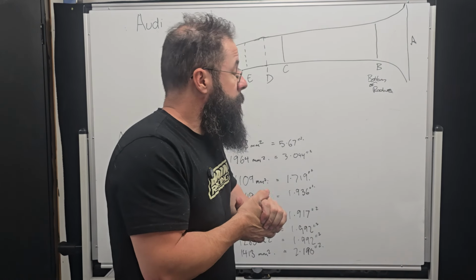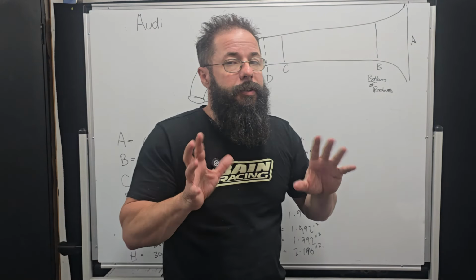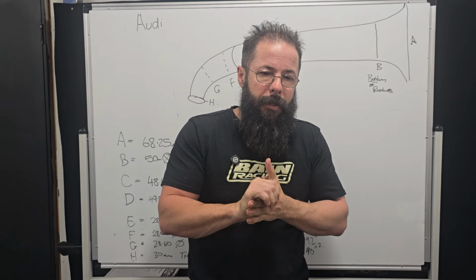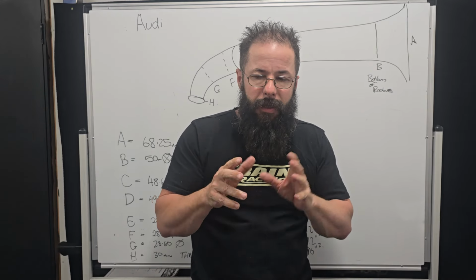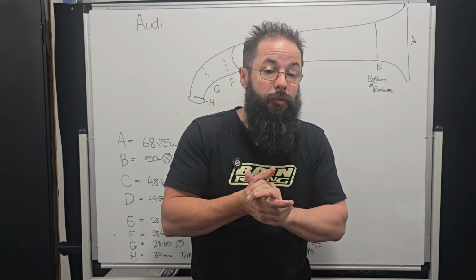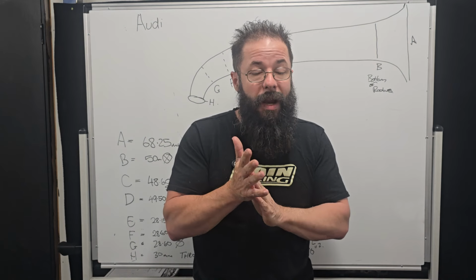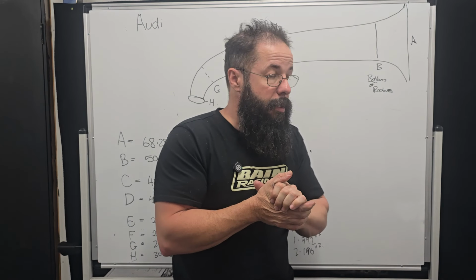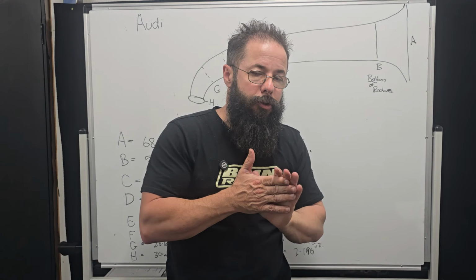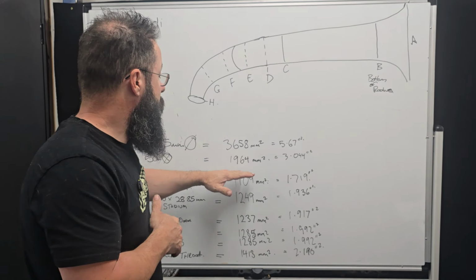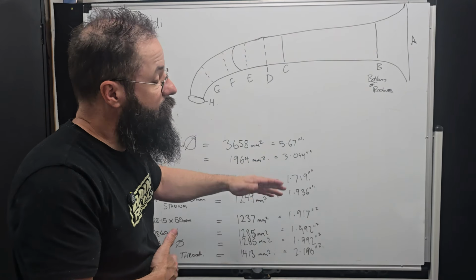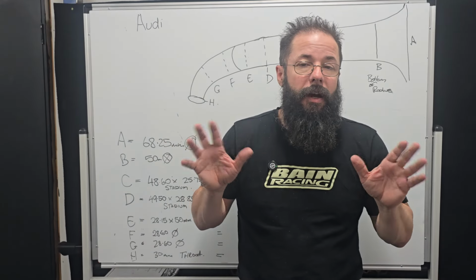Now, I've done a lot of this sort of stuff with 6 cylinders and 4 cylinders, and you look at guys like Plasma Man, and they seem to be on the math fairly closely, and even radius size. We're under 1/2 inch on them now. And on a good induction, so a nice tapered runner at about that 2 to 3 degrees, we're finishing our diameter at about 17, 18, 1900 square millimeters.